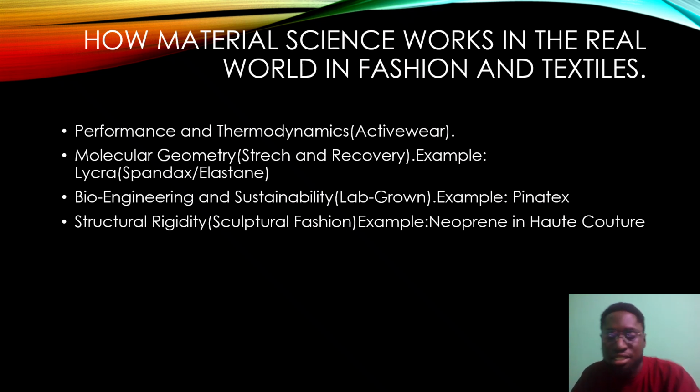Under material science, it's the engineering of the backbone of polymer chains to act like a coil spring. Example, Lycra, spandex or elastane. It consists of hard rigid segments that bond together, providing the structure, and soft segments, which also make it so that when you are running in sportswear, you'll be able to stretch to the maximum that you have.